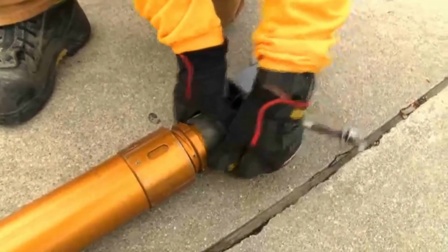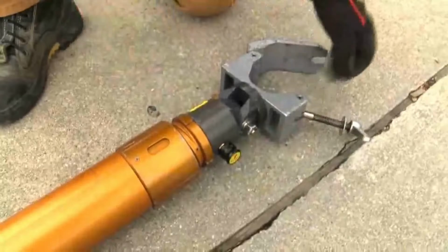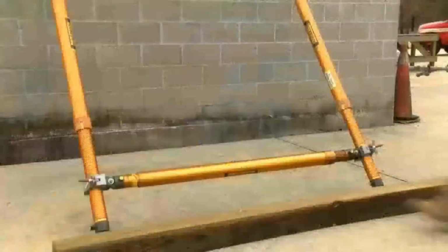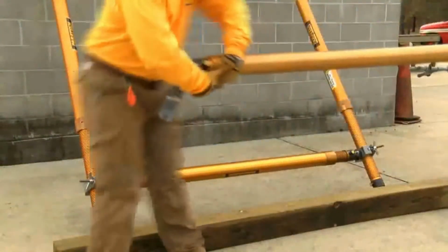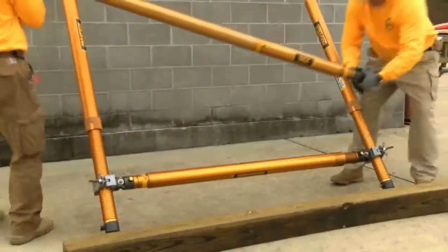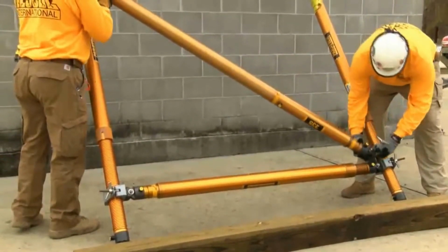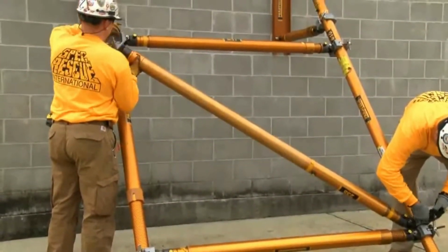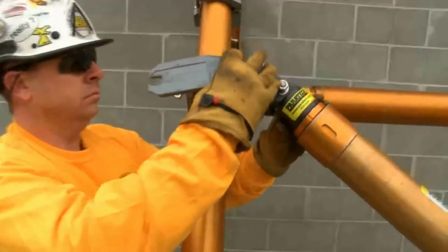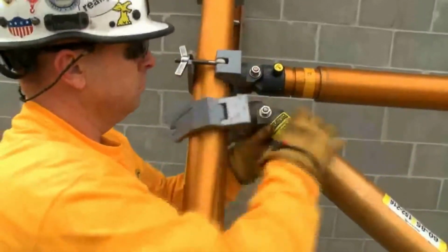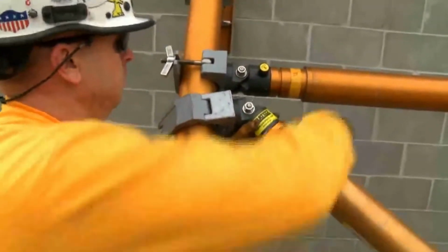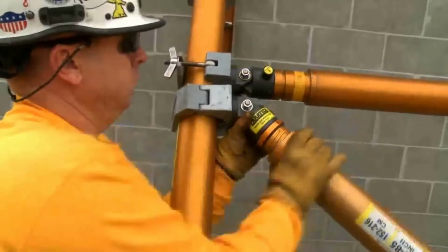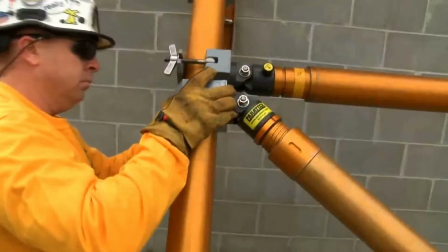Then move the device in and install the first diagonal brace onto the raker system. Take the adjustable diagonal brace that was assembled and attach that to the bottom of the raker first. Notice they always attach the non-movable or non-adjustable end first. Take the adjustable end and slide it up, turning it out to adjust it so the clamps and clevises are tight together, turning the butterfly screw.